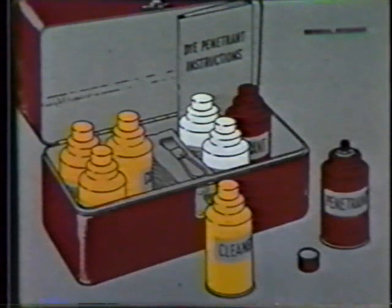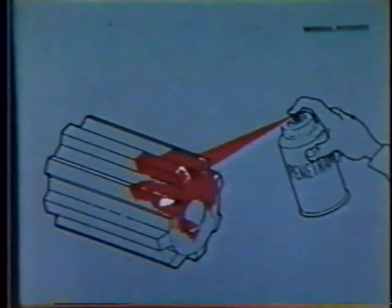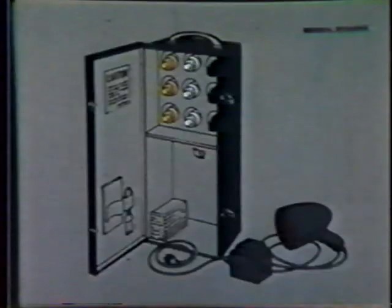Maximum contrast, seeability, is obtained with fluorescent penetrants. Their brilliant glow catches the eye and magnifies. Simplicity and portability are advantages of color contrast penetrants. Kits contain all that is needed in performing spot checks and tests in the field. Materials are sprayed on and wiped off. No electrical power is required. Neither is a darkened area. Slightly less versatile is the fluorescent penetrant kit, but it provides better sensitivity in locating fine cracks.